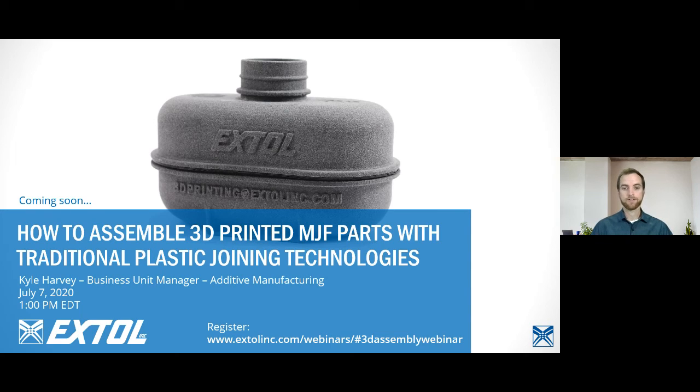And a lot of that is how we orient it. We can make that better, or at least make it so that we're getting the most critical dimensions in the right orientation for you. So that's something that I like to talk through before we print parts, of what are the key features and how can we orient it best for your application.